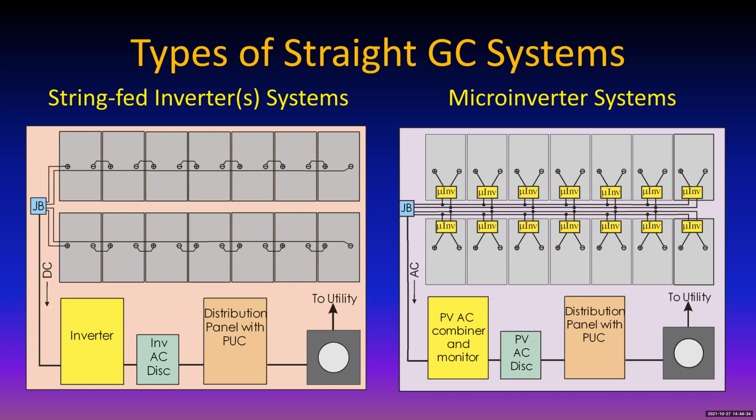There is no more electricity leaving that microinverter, and it's perfectly safe to be up around the roof with all these modules. So you notice all these microinverters are in parallel, the strings are in parallel, all these current sources add, and so you've got 240 volts, and in the case of the more popular 290 watt microinverter, each one contributes 1.21 amps to the system. So if you got 20 of them, you got 24.2 amps. And 40 of them, you got twice that.